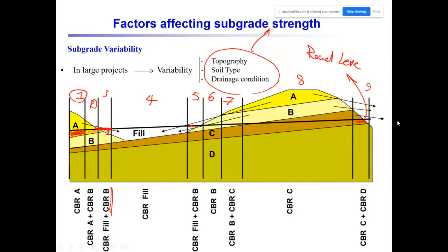So let me see. There was actually another question. I think we missed one question. For the subgrade material, do we use in situ only if proof roll testing passes? Just wondering if we always have to use other material when fails in deflection test. So you need to determine the CBR value. This is a good question.